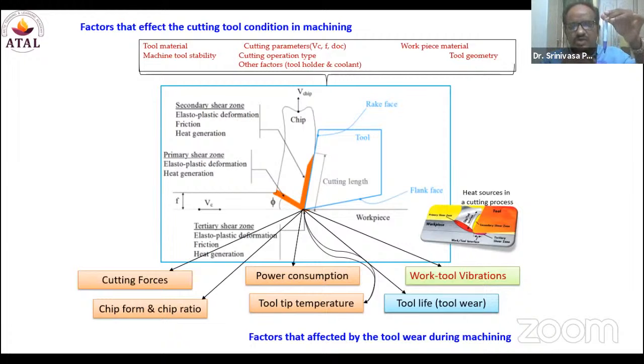Now, this presentation is going to suggest a solution based on feedback collected in the form of vibrations. Why I have considered vibrations as feedback in this system is that, if you go through the literature on machining research, most researchers have worked with cutting forces. And most researchers use Ra, surface roughness, as the most popular parameter in judging the quality of machining.